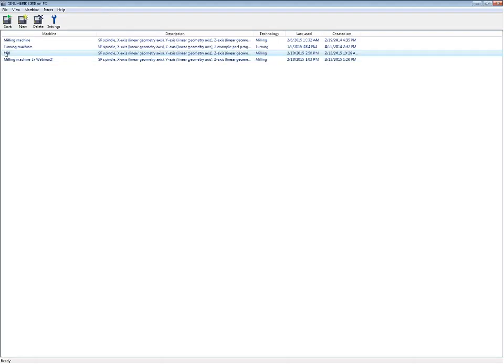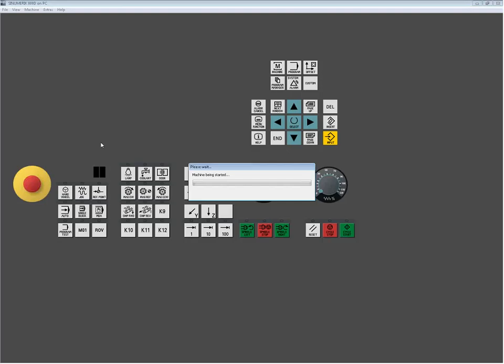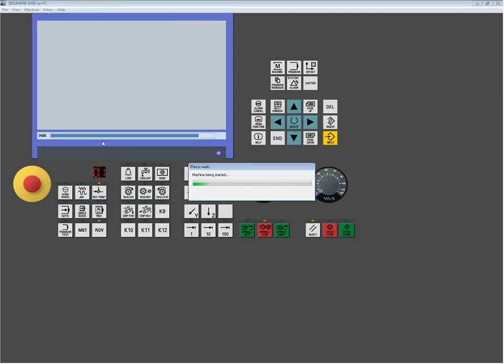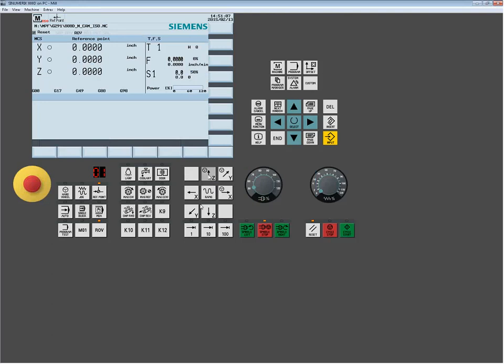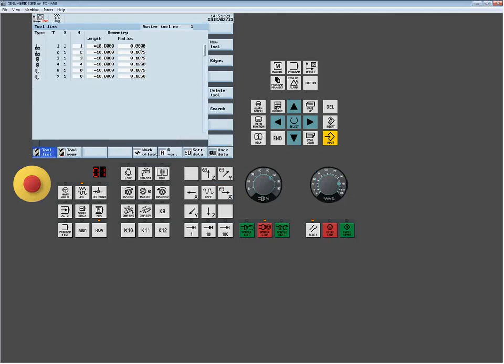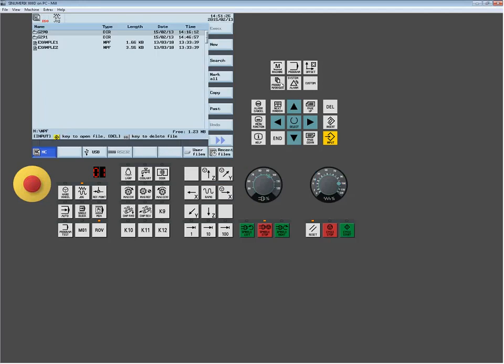I do not have the ability of doing that radius trick that I was showing you before on the Siemens side. You know, those upper level instructions or functions are certainly things that are reserved to when running in R mode. So, you know, those are that and a lot of other commands. As you start to get more in depth in the control, you start to lose when you're in ISO mode. So just be aware of that. Be aware that you are going to compromise or give up some functionality or features when running within this mode.